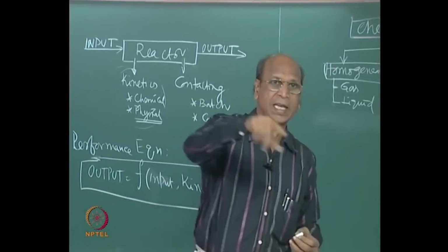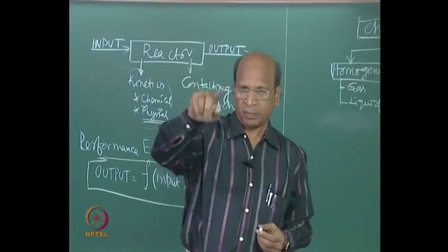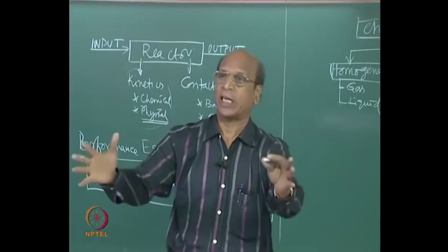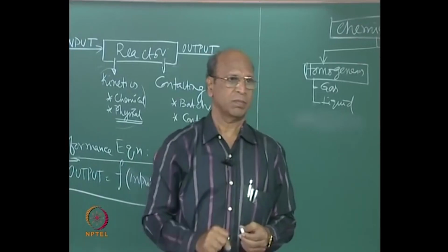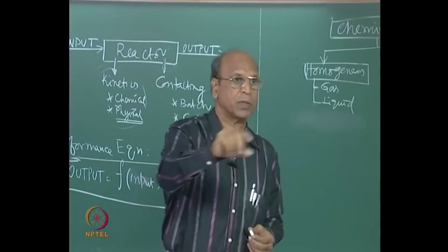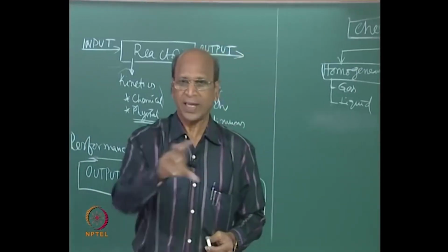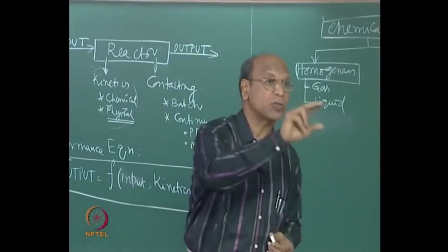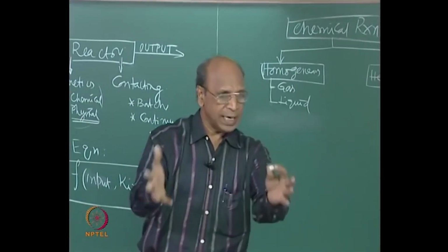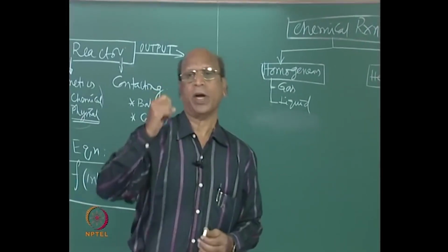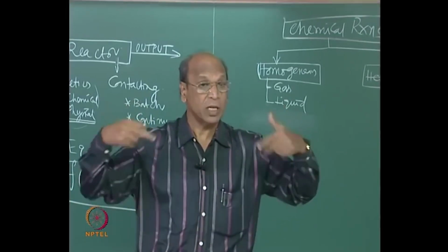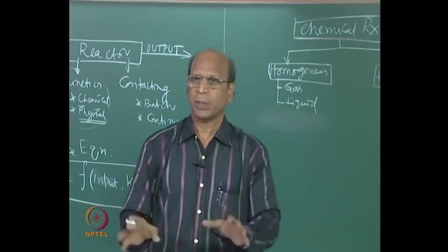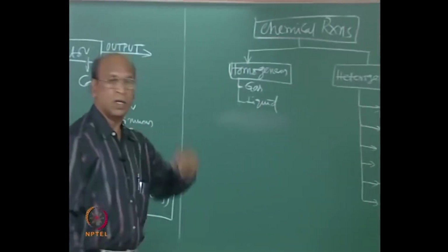That is why we have to clearly say, moles converted per volume of the reactor, that means you are talking about the entire reactor, or volume of solid, that means without any voids. Okay? Like that only, or volume of voids only. Which voids again? Reactor voids or particle voids. You see how much confusion is there. That is why we should have a very clear picture of what we are talking about when we are talking about heterogeneous rates.